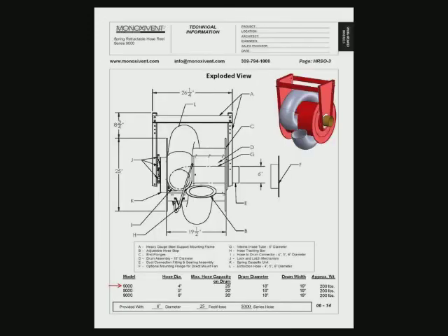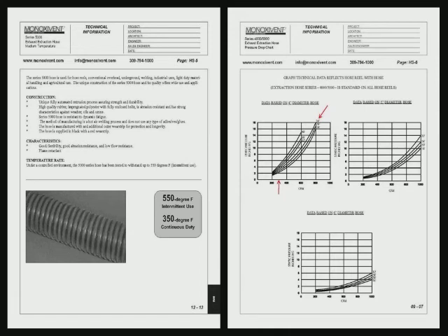Okay, now we had made the initial selections of the equipment. Now we're going to look at the actual data sheets for the equipment that we selected. In this case, it's spring-operated hose reels. I filled it in with 4-inch diameter, 25 feet of 5000 series hose. This is going to be our model 5-9254 narrow body spring-operated hose reel. The hose that we're going to use for this application is our series 5000. It's a medium temperature hose, up to 550 degrees intermittent, 350 degrees continuous duty, and in a tune-up application, that's more than enough.